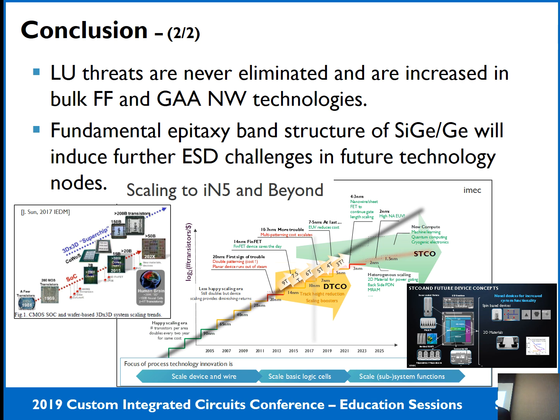Can I have a question? For the rotated diodes, is there going to be a deep implant diode for that too, or do we have a benefit if we were to do a deep implant for the rotated diode? No, I don't think it's necessary to go to deep implant, because the main issue is that it will increase your parasitic capacitance. I don't think it's a benefit to use it.